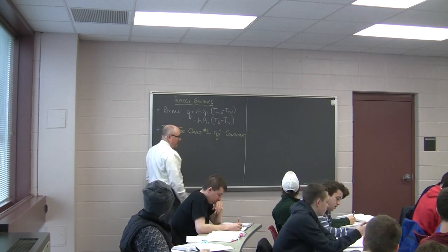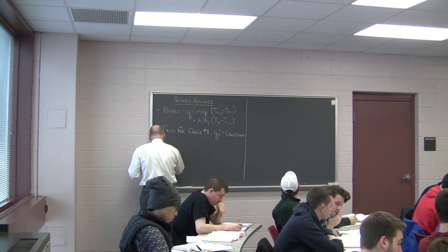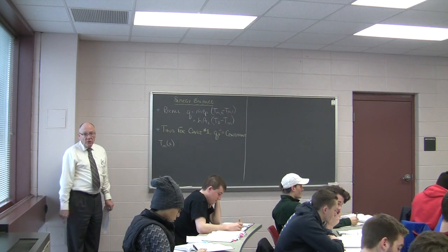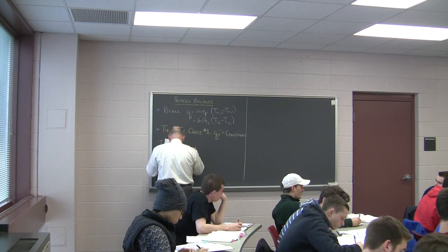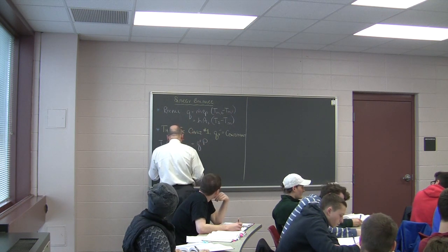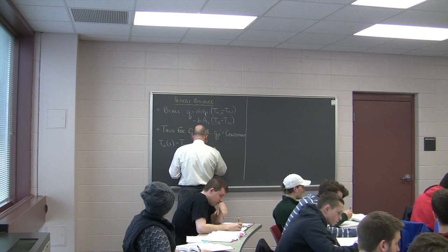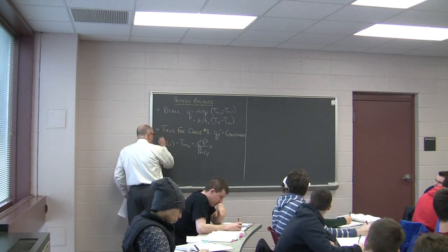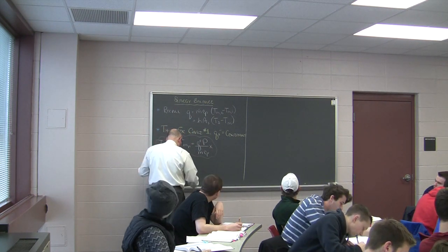This value is constant. And if that value is constant, then we can say that the mean temperature of the fluid at any point X down the flow of the pipe is going to be equal to T in, the temperature in, plus q, the flux, times the perimeter of the pipe over m dot C sub P, times X, the distance down the pipe. And this is one of the equations that you will find very useful. And this is equation 840 in your textbook.